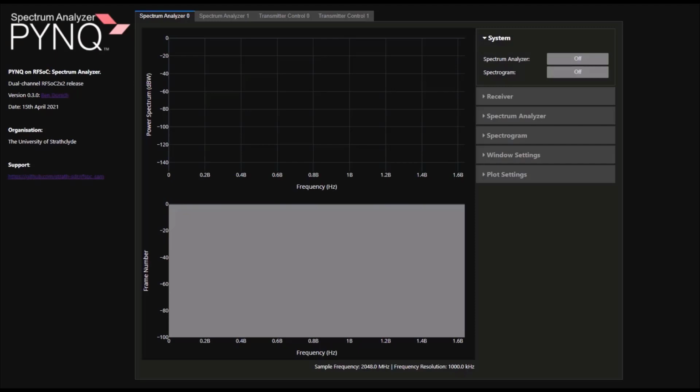It is important to note that in order for this demonstration to operate correctly, bandpass filters have been applied at the input of the RFADC. Without these filters, it would not be possible to remove unwanted frequency components from Nyquist zone 1. The unwanted frequency components normally interfere with our signal of interest, which aliases from the second Nyquist zone.